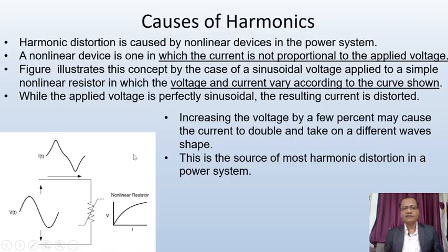Now, where does it really affect? The basic cause of harmonics is nothing but the non-linear load. So what is meant by non-linear load? We'll understand it first and then again go to the harmonics point. Non-linear loads are nothing but loads which do not take current in proportion to the applied voltage.